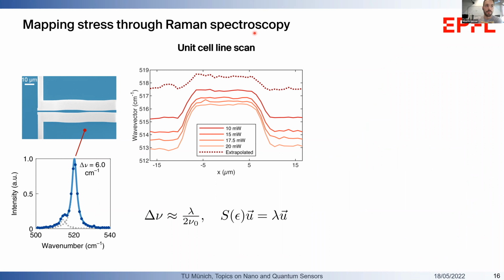If you focus an intense visible laser on some region of the strained silicon on insulator chip, and look at the Stokes scattered light at lower frequencies than the excitation beam, you will see a spectrum like this, with one intense peak at a red shift of 520 cm^-1, which is the frequency of the main optical phonon of silicon without any strain, and a smaller satellite peak at a small redshift from the main peak.